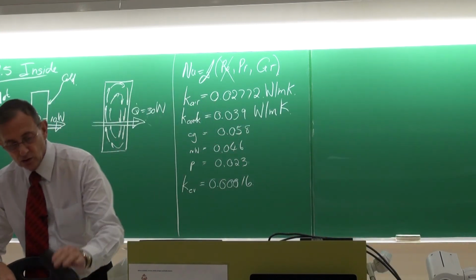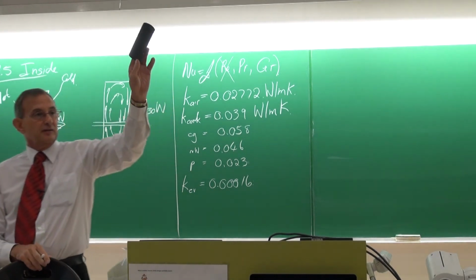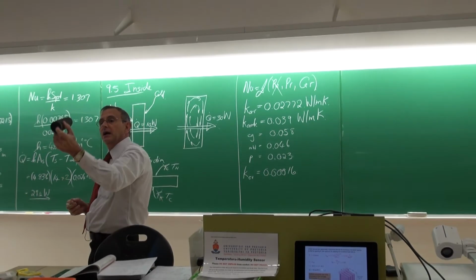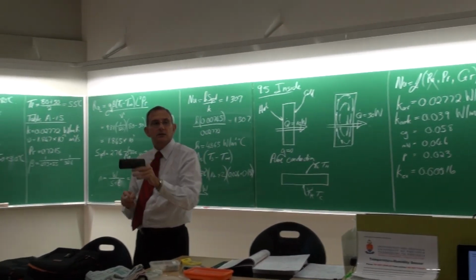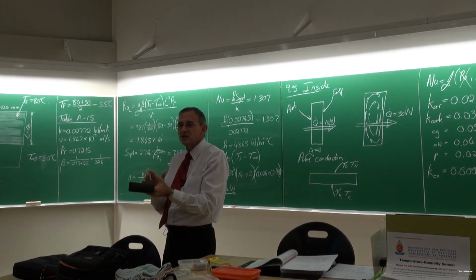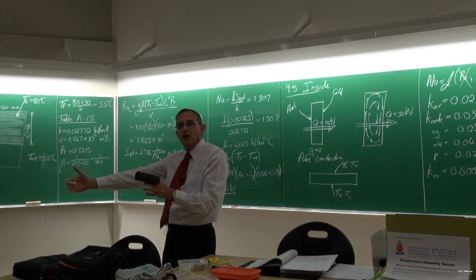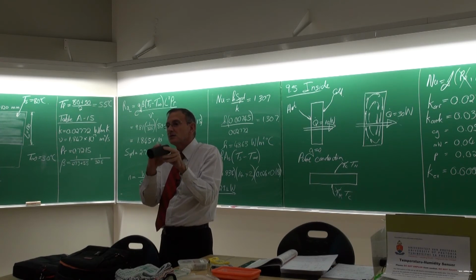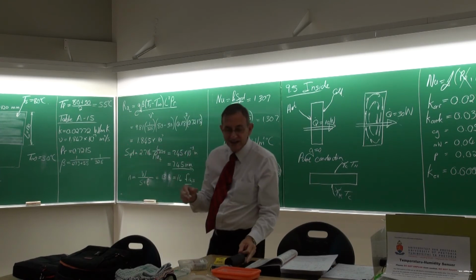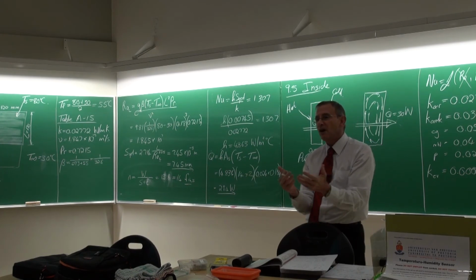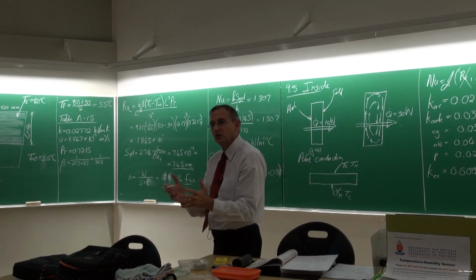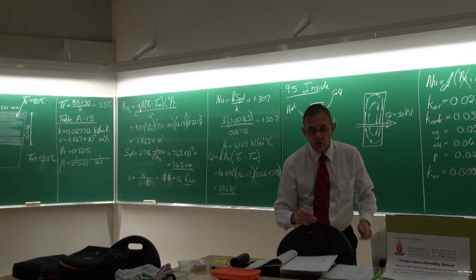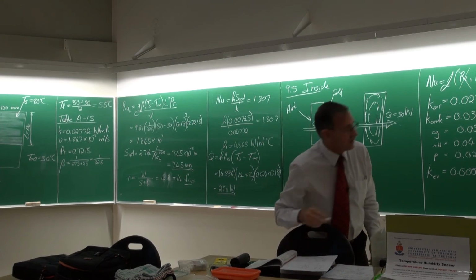In our laboratory, we do lots of heat transfer experiments. I don't know if you've seen this type of material. We call it Armaflex. Okay. And we typically use this as a material on surfaces which are being heated to about 60, 70 degrees Celsius in an environment of 20. Now we need to put on about 300 millimeters thick of this on the tube so that we can decrease the losses to the environment to less than 1%, just to give you an idea. And Armaflex has a K value of 0.036.